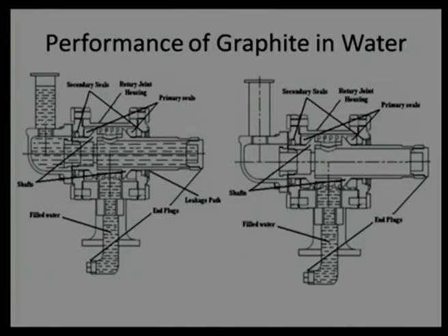So, moisture is necessary for carbon graphite, but too much moisture is more problematic. At a very high level of moisture, there is a higher wear rate, because the transfer of the layer onto the stainless steel is very high, and the thicker the layer, the more brittle the structure, it will get damaged immediately and form wear debris immediately.